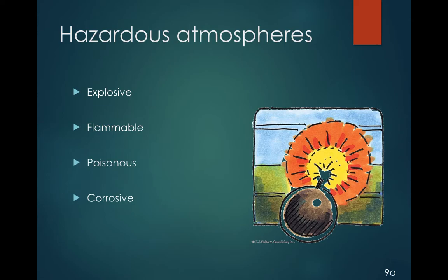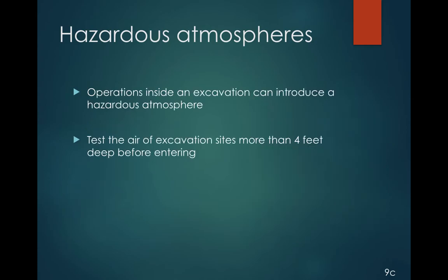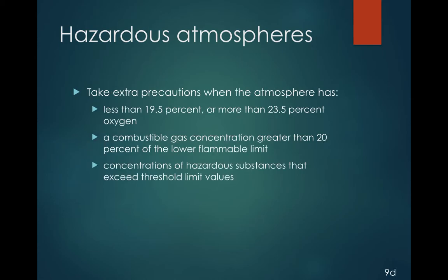We have explosive, flammable, poisonous, corrosive, oxidizing, irritating, oxygen deficient, and toxic. So operations inside an excavation can introduce a hazardous atmosphere. You want to test the air of excavation sites more than 4 feet deep before entering. Take extra precaution when the atmosphere has been established at less than 19.5% or more than 23.5% oxygen, a combustible